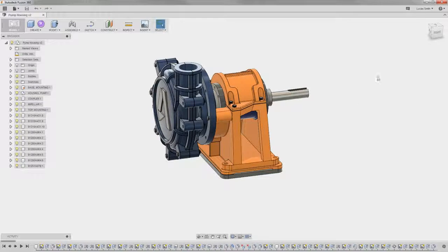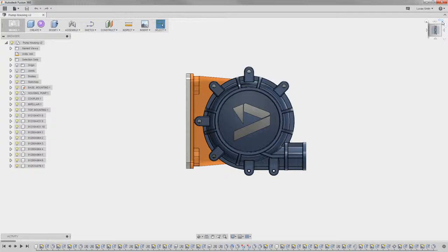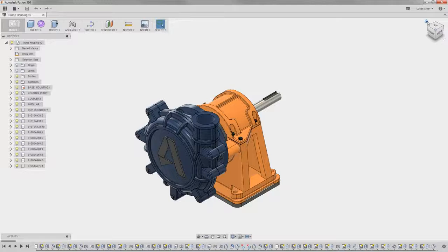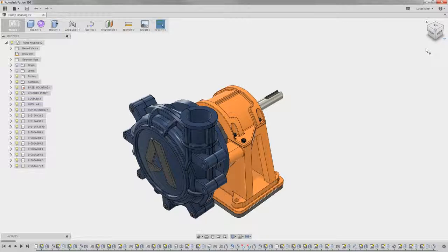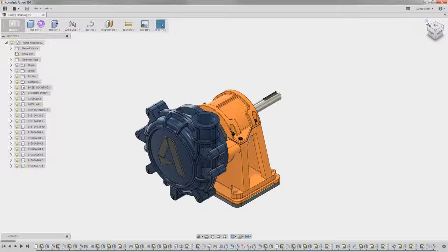The View Cube also provides a quick way to switch between standard views, or rotate the view clockwise and counterclockwise. Clicking the Home icon will take you right back to the default isometric view. If you notice this arrow near the View Cube, an option I like here is the ability to switch to Perspective View, which provides a bit more realistic visualization, and the Perspective with Ortho Faces, which keeps the perspective view until you look directly at a face and it switches to ortho automatically.